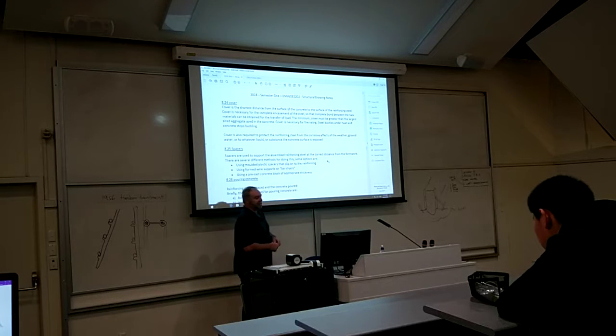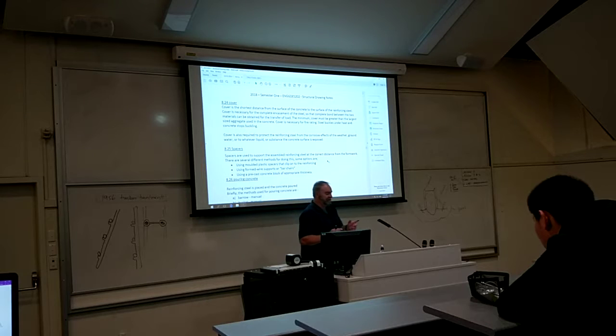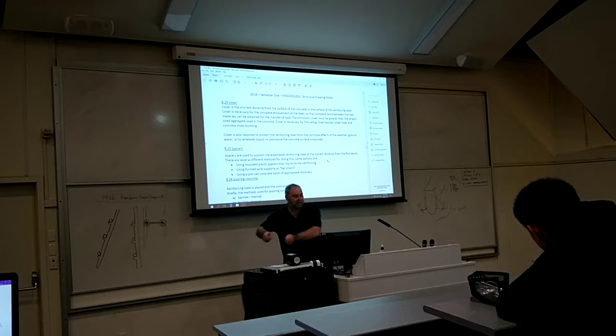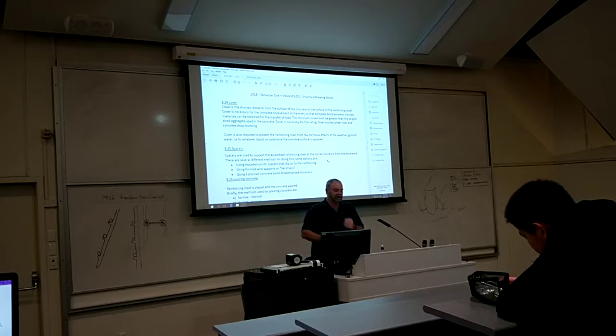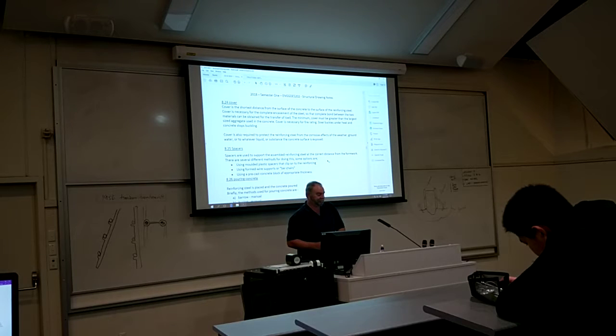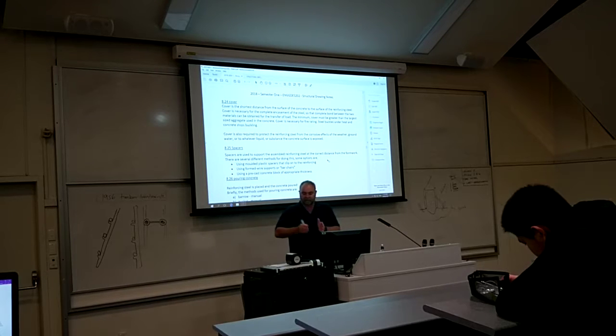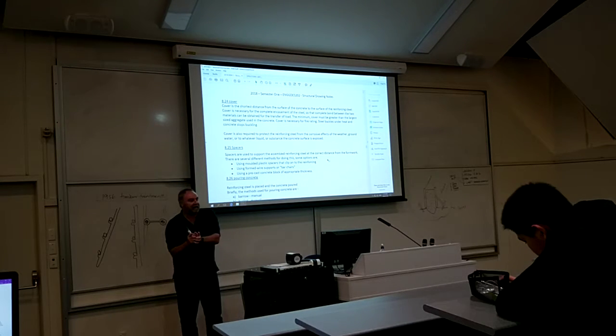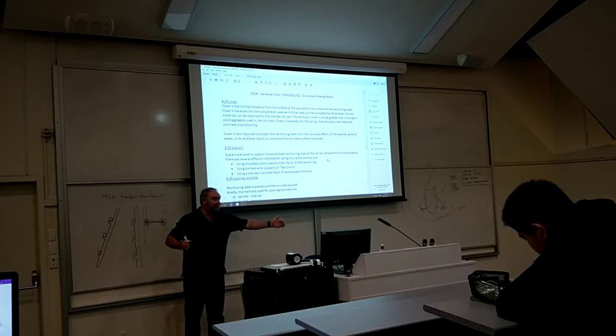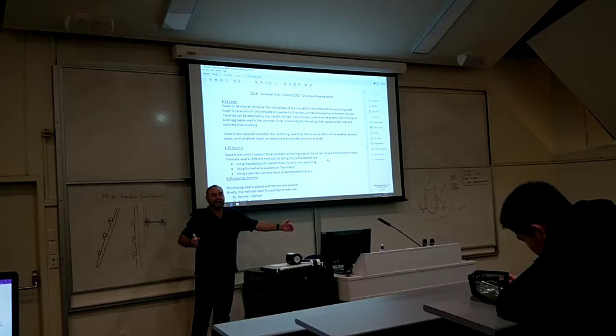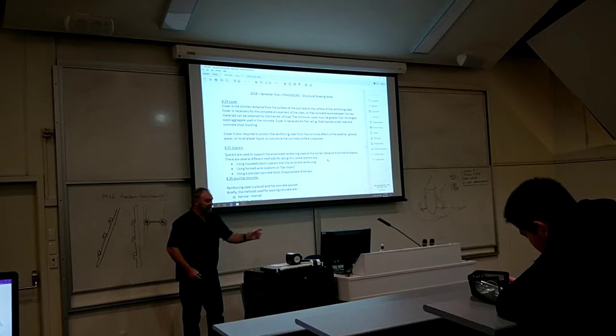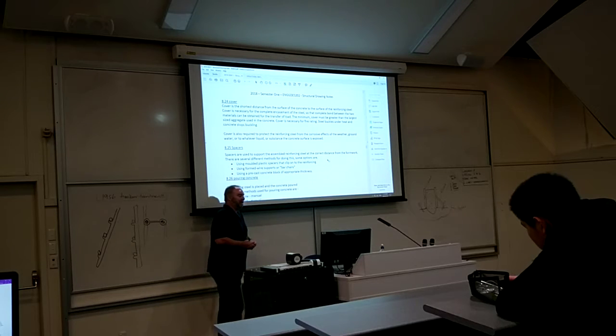If you ever get sent on site and you get told that the minimum distance between the reinforcing bars is say 300, it's quite good to have a little stick or something with 300 measured on it, so you can go along very quickly and measure to make sure none of them are an uneven distance. So when you're calculating how many bars there are, when you're spacing them on your drawings, I don't want to see you go 300, 300, 300, 300, and then get to the end and there's a gap that big. I want to see you spacing them evenly from one side to the other, so you might end up with, say, 287.5 all the way along, because that's the way it will be done on the site.